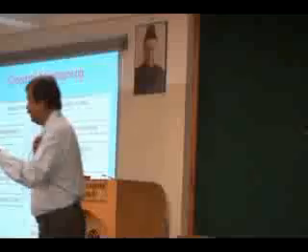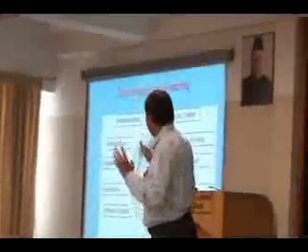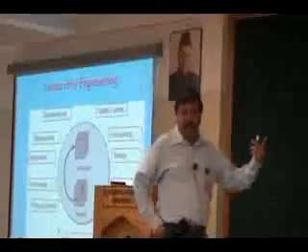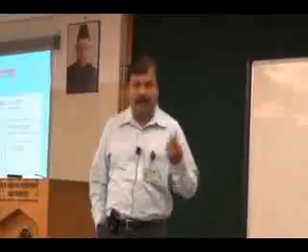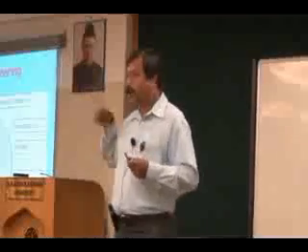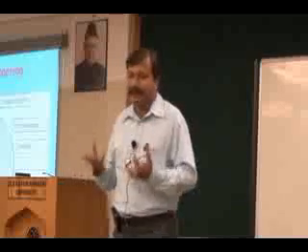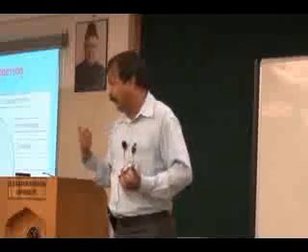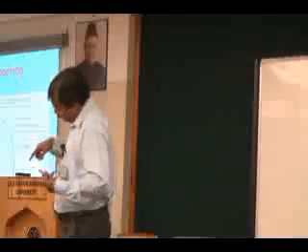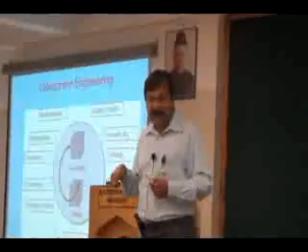When I have to do that, sequential engineering is not going to work, and I have to resort to concurrent engineering. How do I approach the problem? In concurrent engineering, I approach the problem with a cross-functional team, wherein representatives from various departments find a place and together take up the design issues so that I have all the inputs: inputs regarding manufacturing, testing, maintenance, recycling.